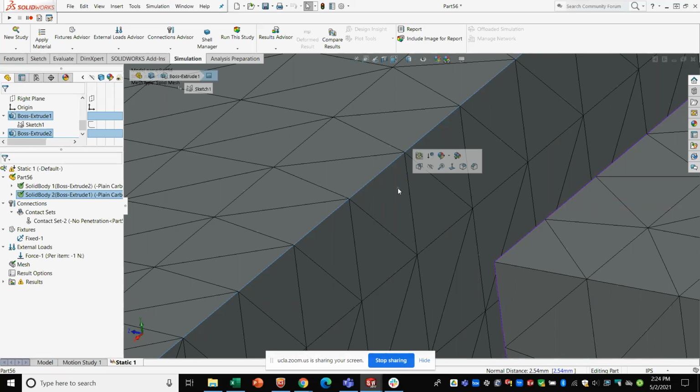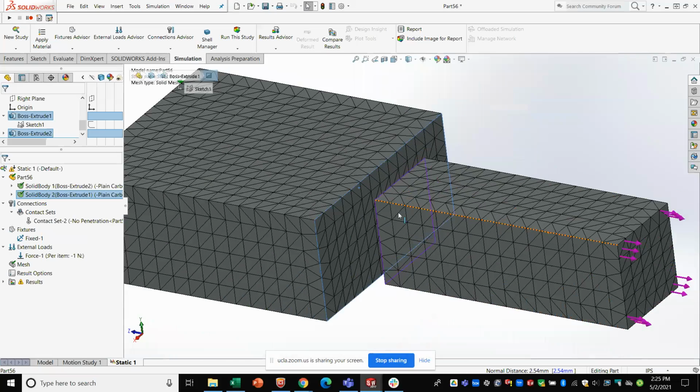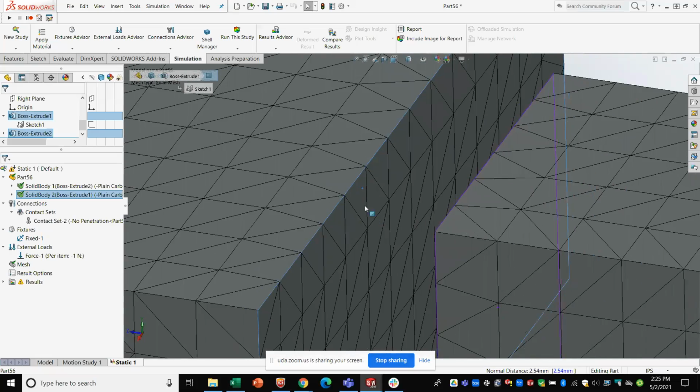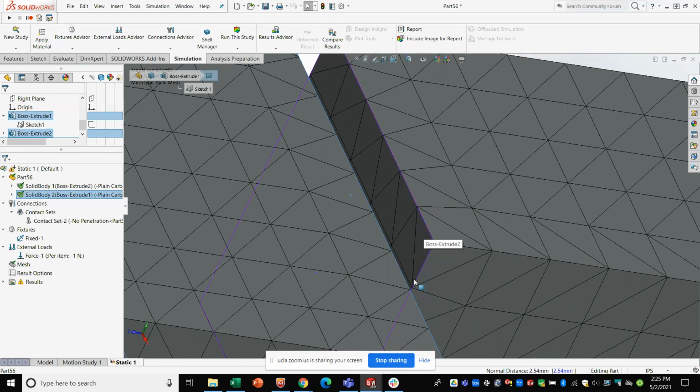And that triangular element is basically a target. What I mean by that is the computer is going to apply the load to whatever faces have a load applied to them, and then check whether a normal force exists between this invisible triangle and any other invisible triangle on the opposite face that you declared as the source for that contact.